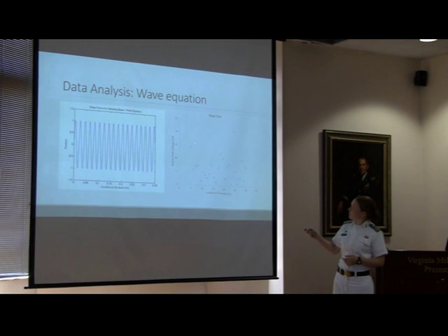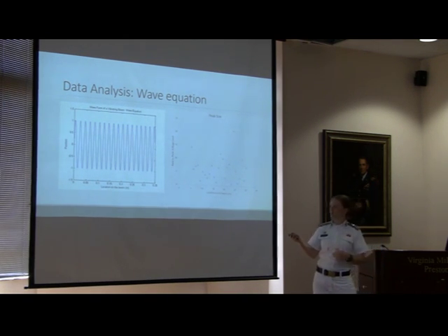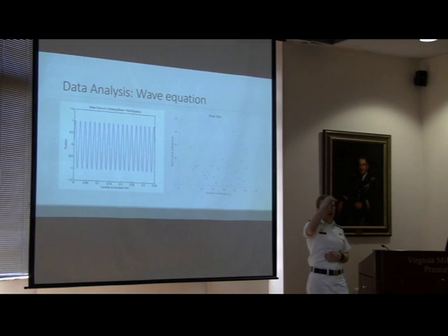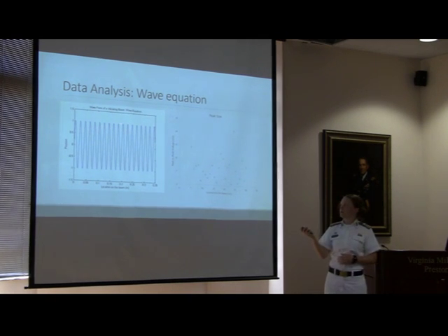So if we look here, what we want to do to match up the accuracy of the model with the data is to find these peak points and these low points. So this peak is at 23.8, I believe it was. So we look here at 23.8, and we'd expect to see it at one of these peaks, because this is where the most vibration is happening, so we know that it's at a peak, or at least very close to one of these peaks.